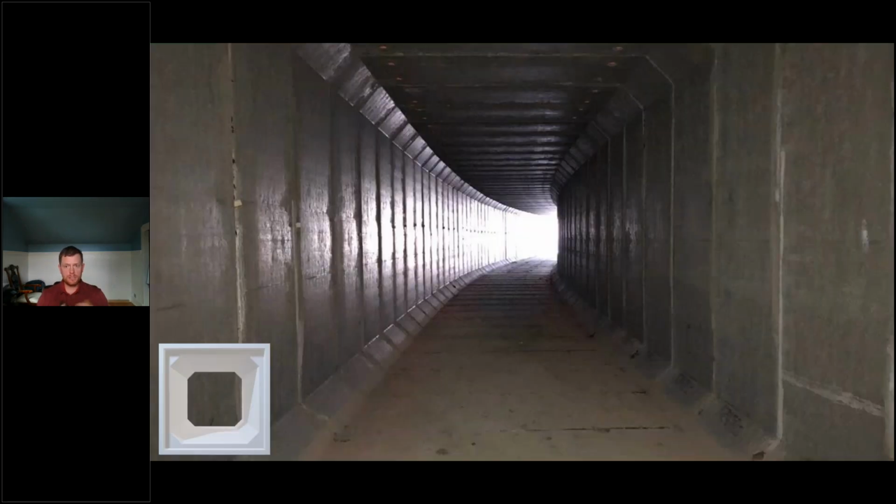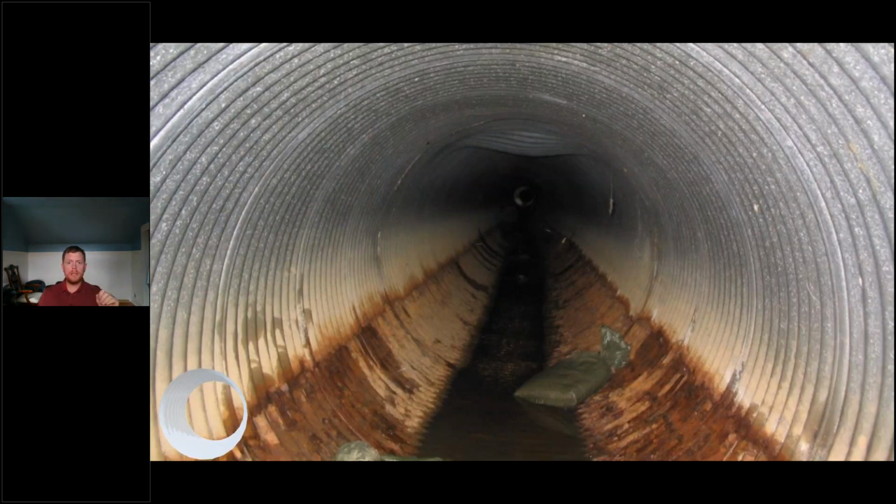So here's an example of a freshly installed box culvert job. Again, you can see that those lines, that wall is nice and straight. It's going to have a really good Manning's n. This is also going to be in that 0.012 range, just like the concrete pipe. Now, this is a picture of corrugated metal pipe, and yes, this is in really bad condition, but for a second, let's focus on the top half of this pipe. So you can see that we have corrugations in there. The water is going to hit each of those little corrugations. It's going to build some turbulence, and we are going to constrict flow just with a standard corrugated metal pipe.